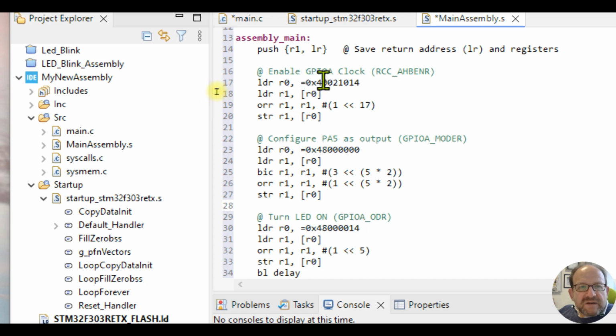You just have to plug in your R0 value, whatever that value is. You get the content from that location into the R1 register, and then you modify it here and then you store it back. If you just get that value and then modify and destroy the other contents, that might harm whatever is going on throughout the whole GPIO or any clock process.